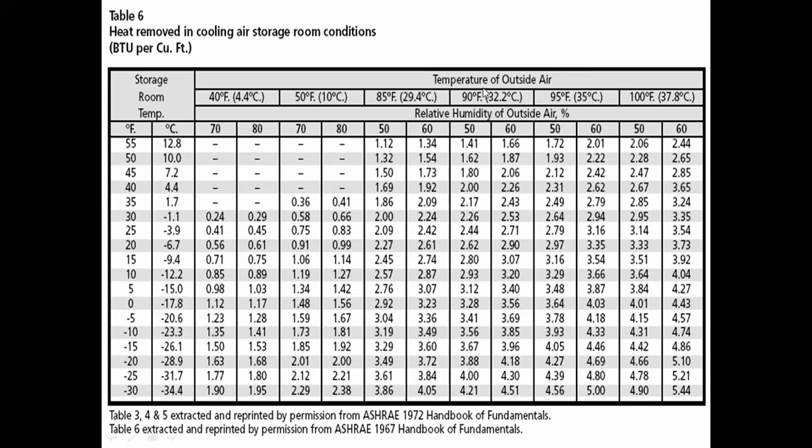So temperature of outside air, outside temperature is also given. So here, what is our outside temperature? This is the outside temperature, right? 95 degree Fahrenheit and 35 degrees Celsius. So what is our normal best humidity ratio? Relative humidity, it will be 50%, correct? Normally it will be 50%. So outside temperature is 95 degree Fahrenheit, choose this one and take the relative humidity as 50.